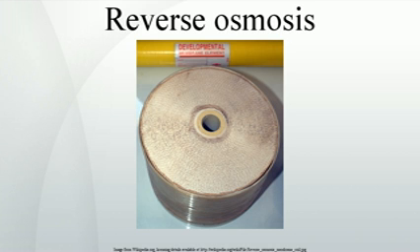It is also used to clean effluent and brackish groundwater. The effluent in larger volumes, more than 500 m3/d, should be treated in an effluent treatment plant first, and then the clear effluent is subjected to reverse osmosis system. Treatment cost is reduced significantly and membrane life of the reverse osmosis system is increased. The process of reverse osmosis can be used for the production of deionized water.